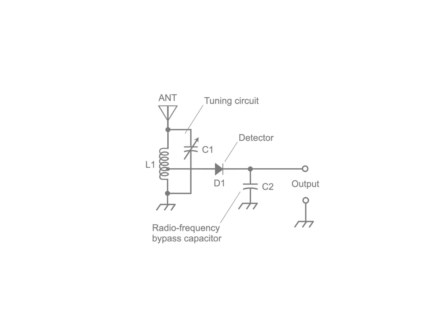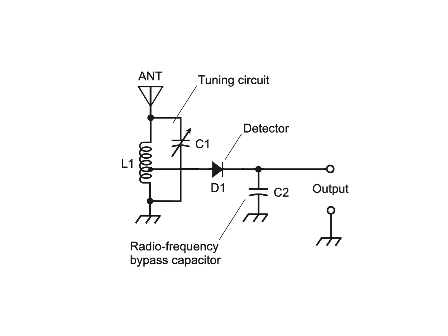This slide shows a crystal radio receiver built with an antenna, a tapped air core inductor, a variable capacitor, an RF diode, and a fixed capacitor. The term crystal comes from the original construction of RF diodes as they emerged in the early 1900s. In order to get a one-way current gate to act as a signal detector, or demodulator, radio experimenters placed a piece of fine wire called a cat's whisker into contact with a piece of crystalline lead sulfide called galena. Today, semiconductor diodes do the same thing as those old crystals did, even though modern RF diodes don't look anything like crystals.